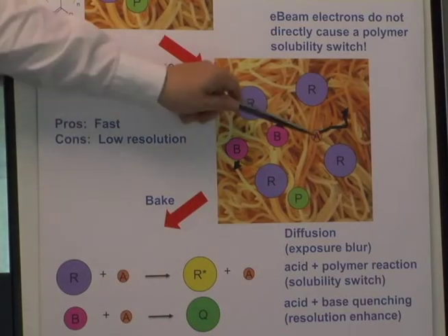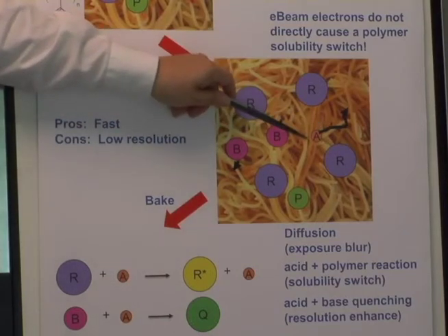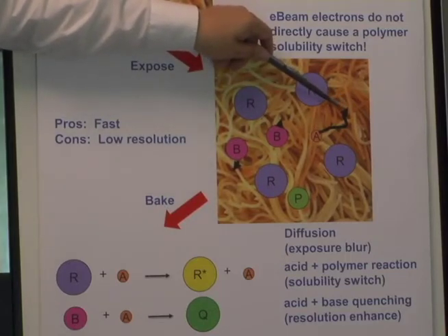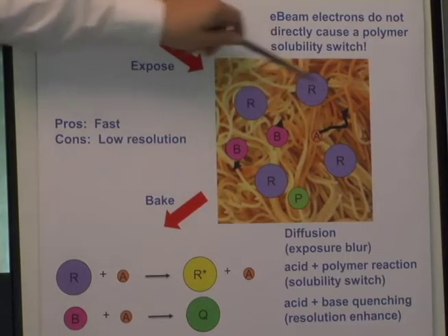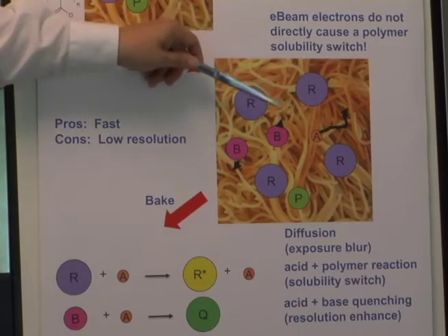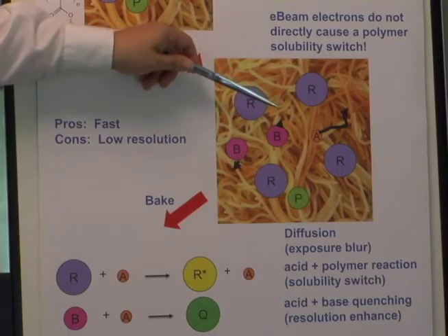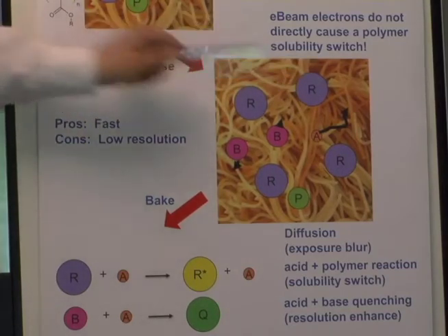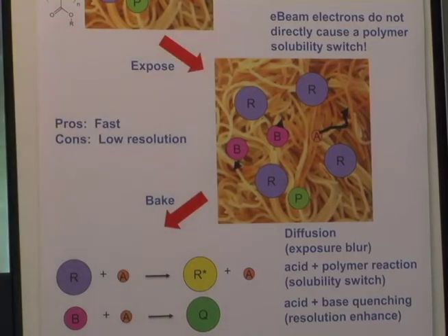Now next, the acid itself is small enough such that it can diffuse over tens of nanometers inside the resist during the post-bake. This diffusion is effectively a blur, which will then sit on top of the forward and secondary electron scattering. Given its length scales, it turns out that this diffusion itself represents the majority of single Gaussian forward scattering in mask models that are in use today.